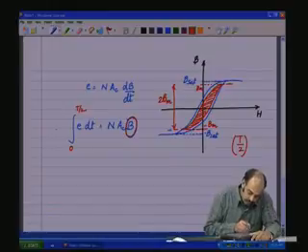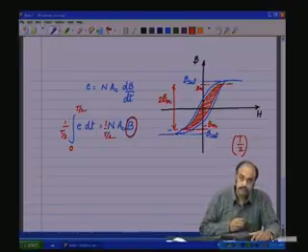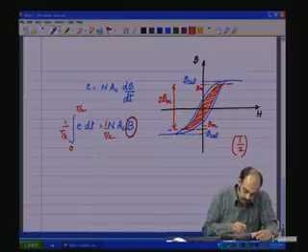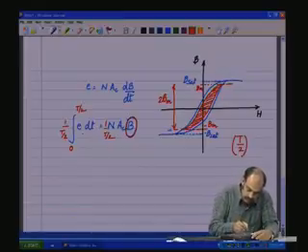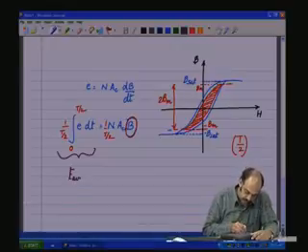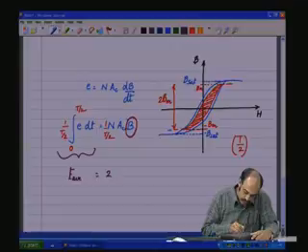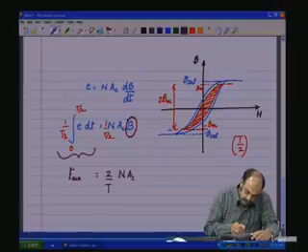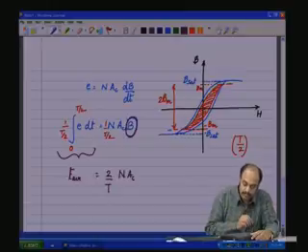So, let me multiply throughout by 1 by T by 2. This portion is nothing but the average voltage E average across the coil, and this is 2 by T n a c, and the flux that has swung from minus Bm to plus Bm is 2 Bm in a span of T by 2.